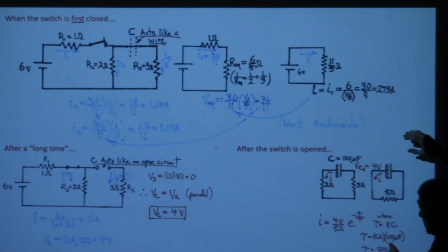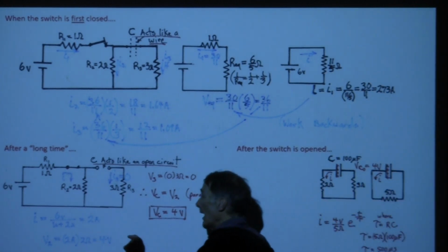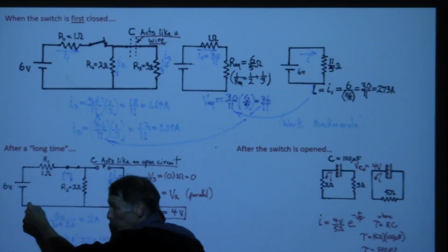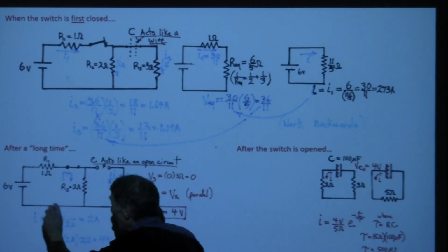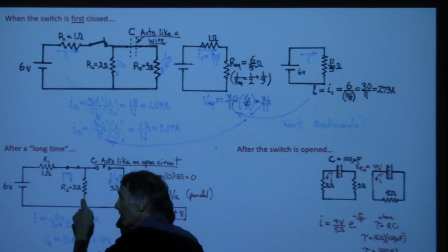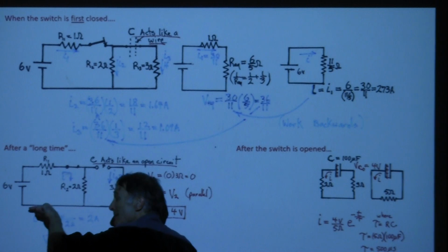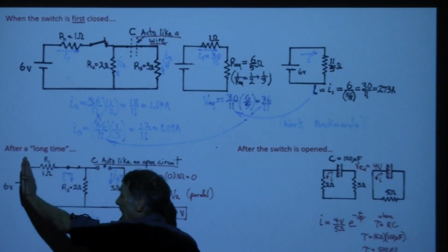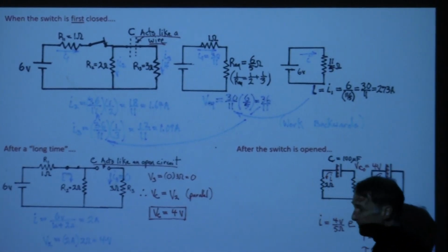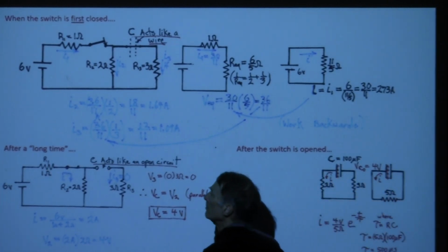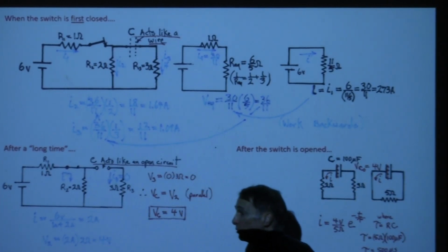I probably overcomplicated it by saying that there is still a current from a left loop in the 2 ohm resistor. I would say that once this switch is open, that kills this whole branch. Even if I have this connected here, this switch opens, there's nothing flowing out this way, there's going to be nothing flowing back in. That's why there will be only the current between the 2 resistors and the capacitor. It's shared just between them.